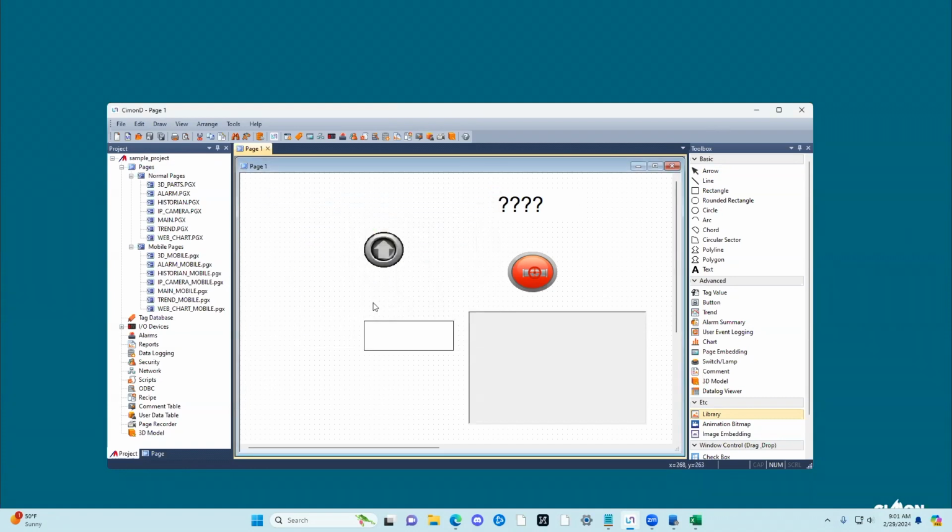And then there is page recording as well. So page recording not only allows you to audit your project's utilization, but it also allows you to troubleshoot your project. So say a certain alarm went off, right? You would want to record the page to see what else happens when an alarm goes off. So you can track up to like 60 minutes of what is happening on a certain page when an alarm goes off or is turned on rather.